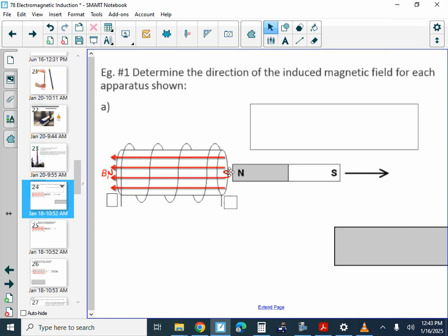Then you could go on to ask, what direction would electrons be going to make that happen? By the left-hand rule, my thumb points to the left, obviously, for the north, and that forces my fingers to curl down in front. So the wire on this side would have electrons going down and out there. If we're talking about current, we'd list that as the opposite way. This is electron flow, this would be current. I always like to put it in quotes because it's kind of ridiculous that we still pretend that positives are flowing. But there's the north, and the south that I already wrote in.